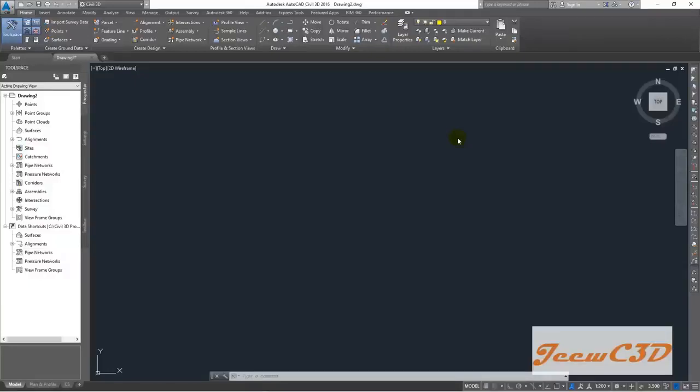I hope all of you have this drawing open by now without closing it from the previous video. This drawing is open using the new road template which I made in the earlier video. Now what I am going to do is import points into this drawing. To do that, go to the Home tab. Then you have something called points here. You click this drop down.